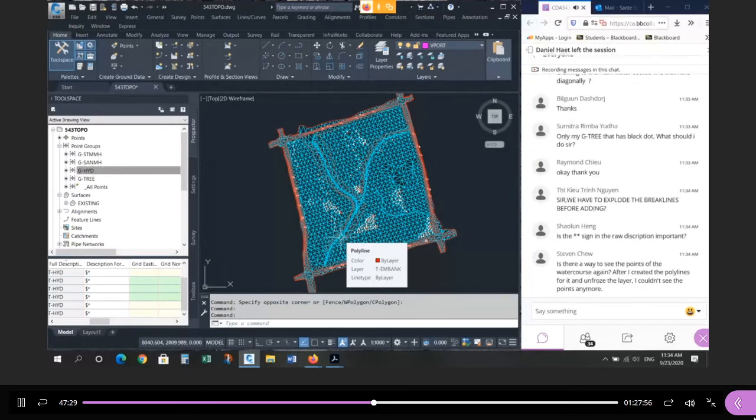It's not that critical in this drawing, but it's good practice because later at work, you might have descriptions that are indexed. You might have tree 1, tree 2, tree 3, tree 4, and you want them all on one layer or in one group. So the asterisk is what's called a wildcard. It only looks for tree, and then if there's a 1, a 2, a 3, a 10, or whatever after it, it'll include all of them, right? So it's good practice to use these wildcards. They're not necessary, but it's a good habit, and that's what I do.